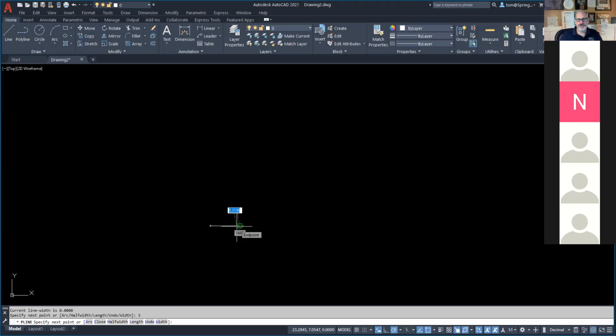So what we just did there is we drew a line at 3 inches. Now, I could continue to pull over to the right, but now I want to go 45 degrees. So I'm going to pull it right here, and watch what happens. When I pull it up, it locks in at 45 degrees, and my hands are not on the mouse. It's doing it automatically because I set it up. So now, in the same way it used to track at 0, 90, 180, and 270, I'm getting these 45-degree angles too. So I type in 3 again.